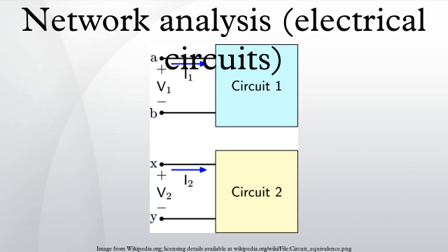These kinds of networks can be analyzed using Boolean algebra by assigning the two states to the Boolean constants 0 and 1. The transients are ignored in this analysis, along with any slight discrepancy between the actual state of the device and the nominal state assigned to a Boolean value. For instance, Boolean 1 may be assigned to the state of plus 5V. The output of the device may actually be plus 4.5V, but the analyst still considers this to be Boolean 1. Device manufacturers will usually specify a range of values in their data sheets that are to be considered undefined.